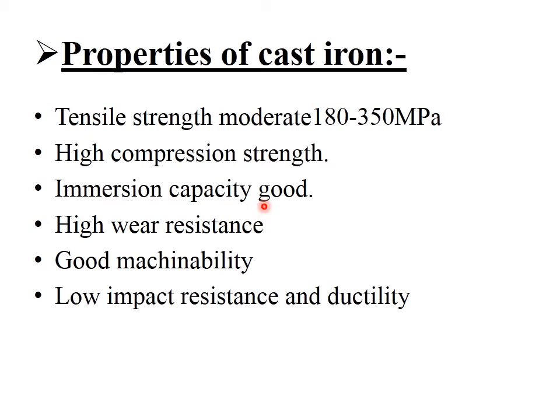Very good damping capacity, good wear resistance, machinability. So one can machine cast iron very easily. And low impact resistance and ductility. So these are the inferior properties we can say that cast iron possesses: low impact resistance and ductility.